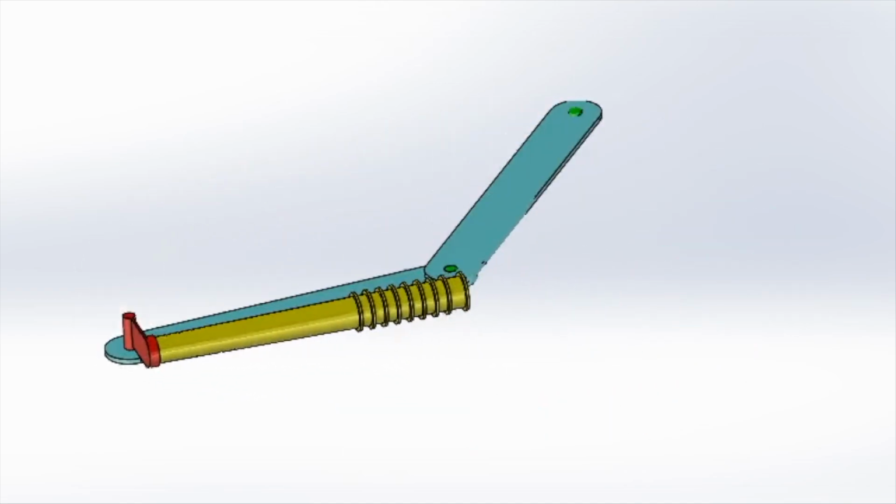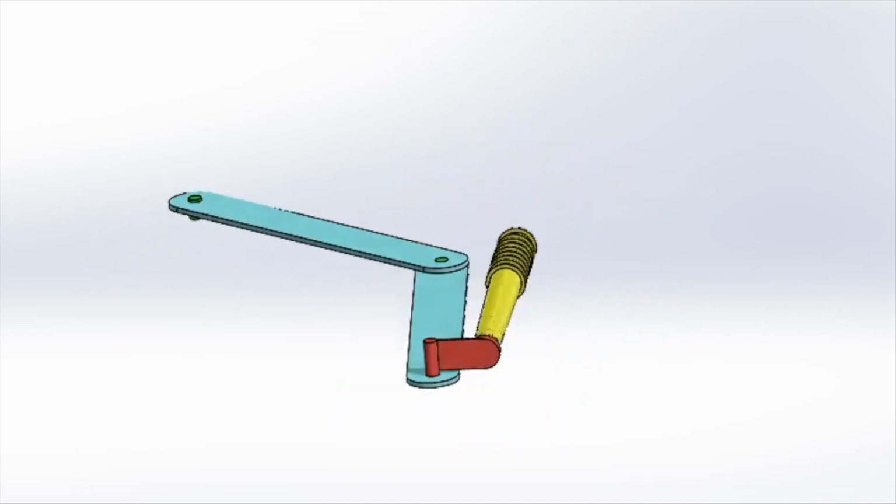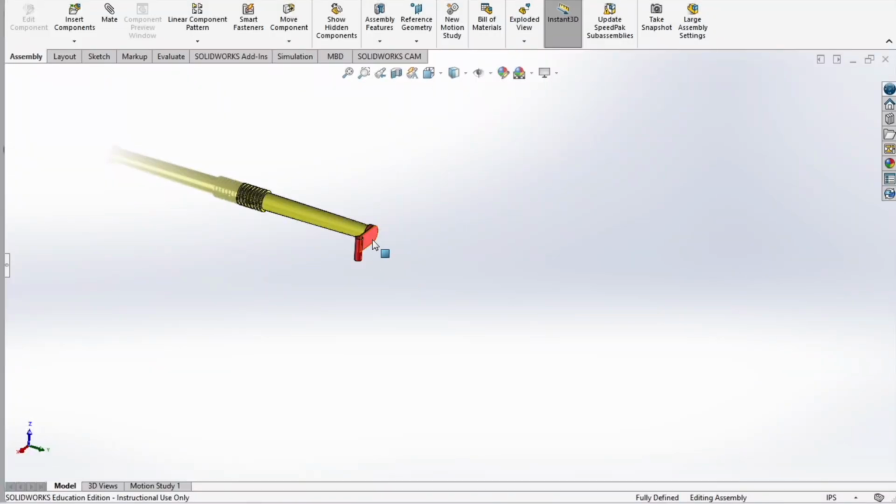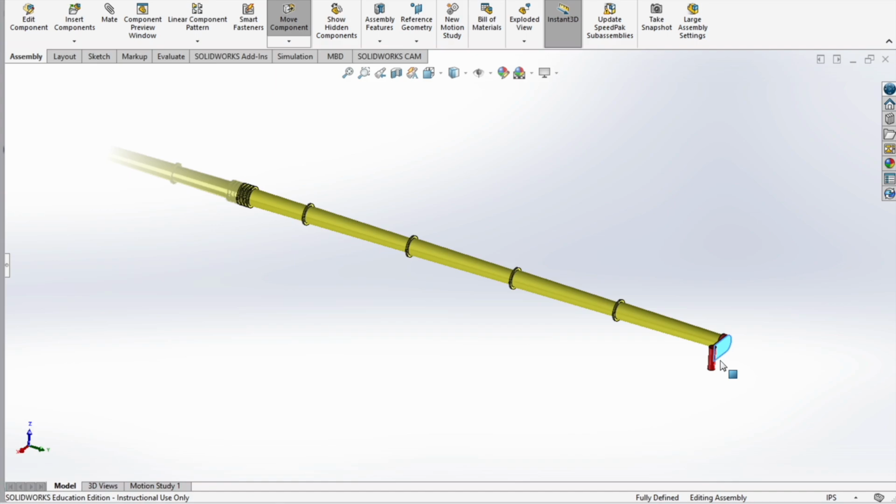The end of the final tube has an adapter that is fastened to 2 linking arms that will eventually connect to the end of the door. When the piston assembly experiences a force, the rod subassembly will use that force to expand its volume and extend the rod. This will divert the force on the piston into pushing the door open.